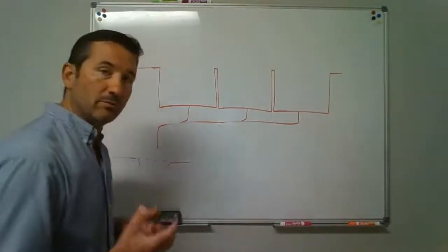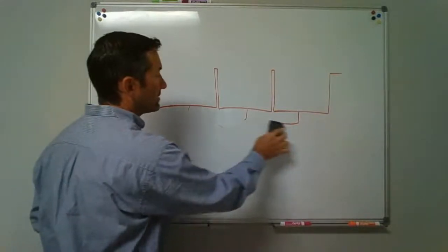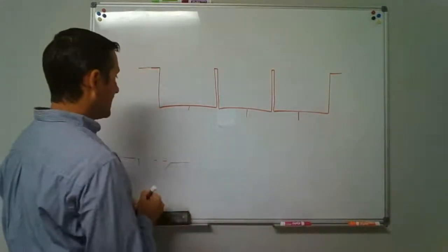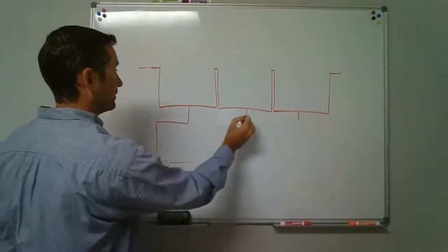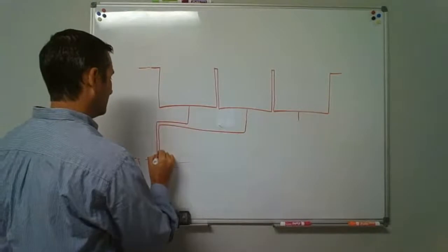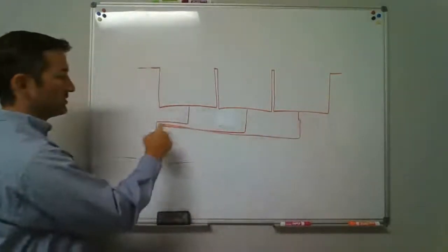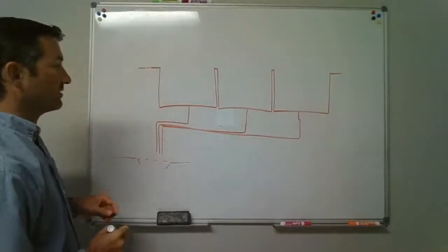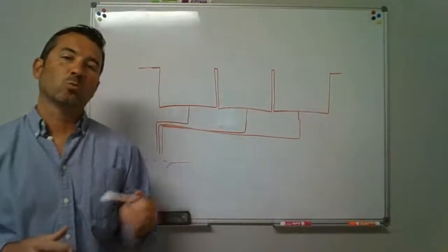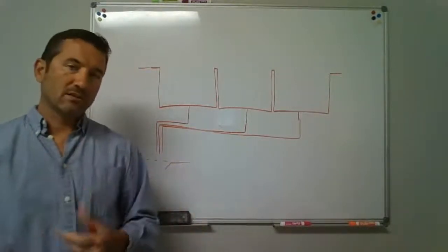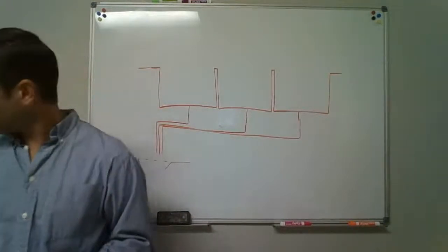So this is going to look a little bit more congested under there than what they used to be, because now they're saying you're going to have 3 independent pipes over here over top of this that are going to discharge in. I guess you have the chances of one not affecting the others as much. If you get one that's blocked up, your other 2 are still working for you.